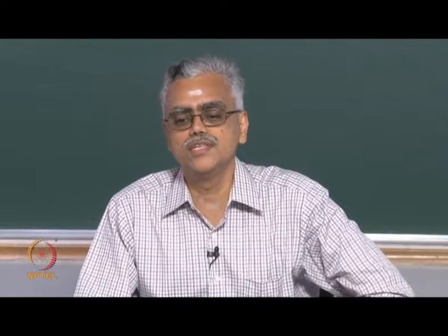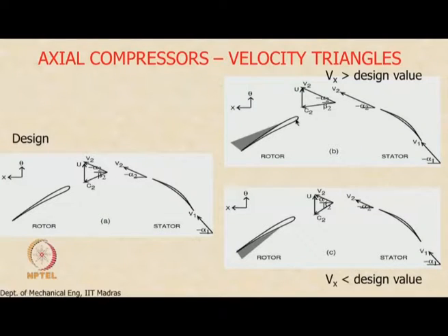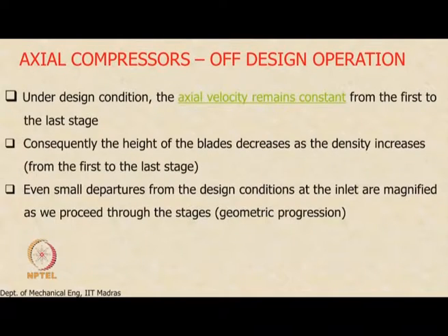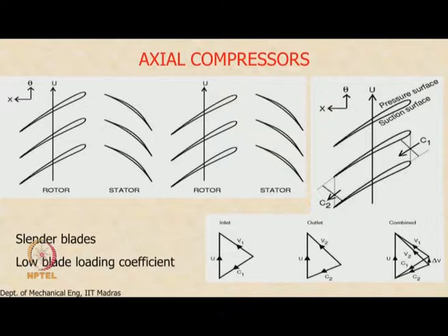So, that means the flow is incident like this upon the blade, it is not incident tangentially, which means that you can see that the flow will go this way, and there is going to be a region of separated flow on the suction side of the blade. This I think is what we call a suction side, correct. Let me just check that quickly. Yes, I am sorry, that is the pressure surface.